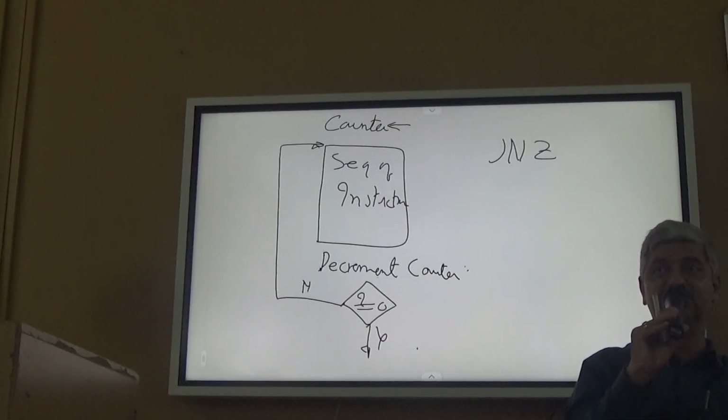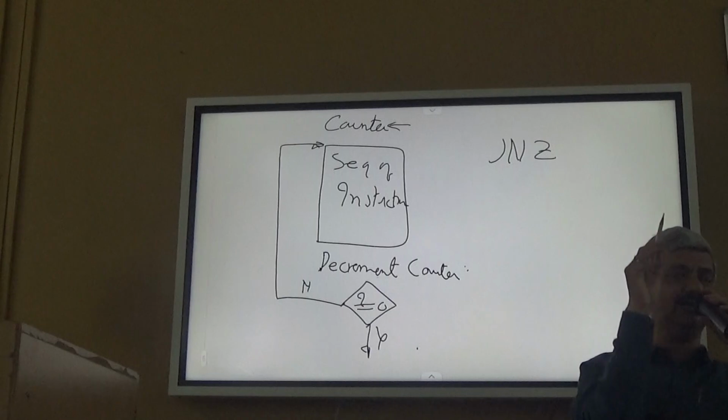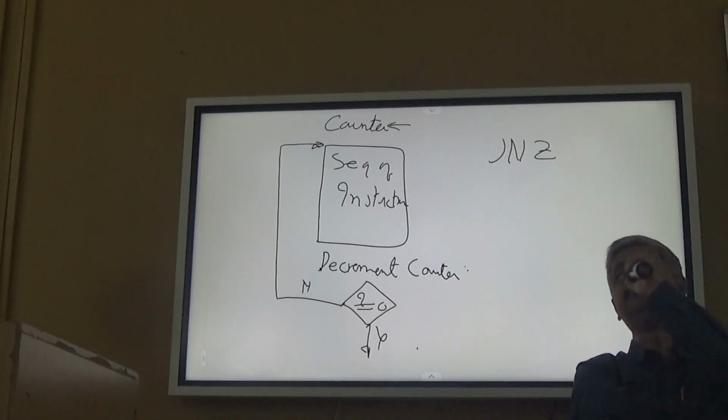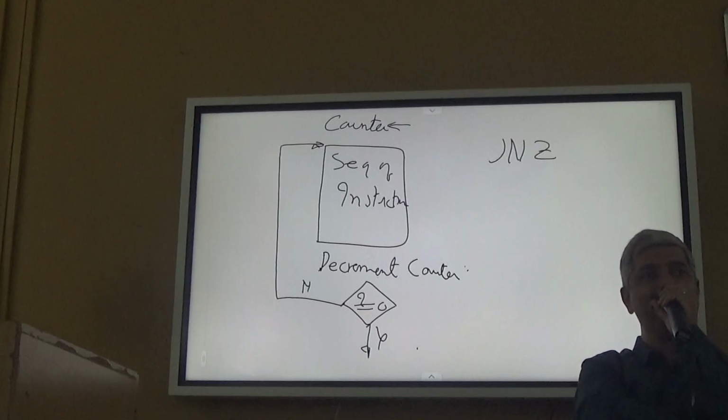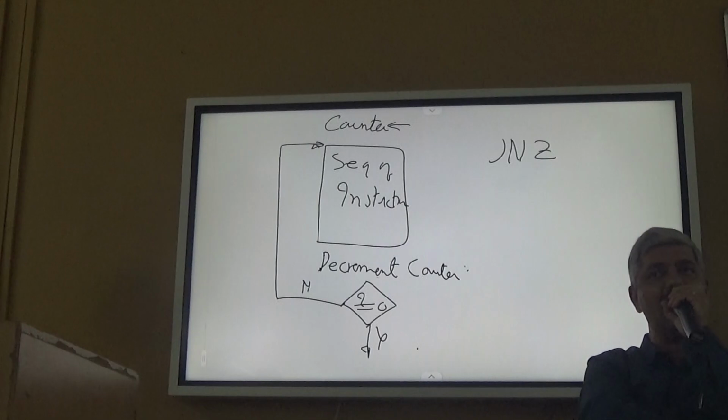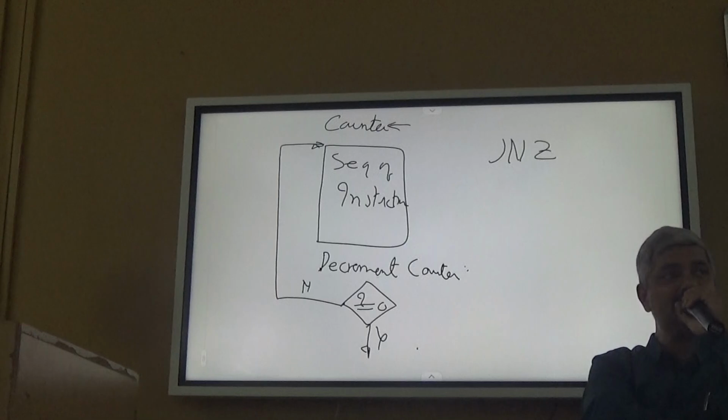Other flags we will discuss later. Zero and carry flags are affected after every arithmetic or logic instruction, and they provide the status of these two conditions when the last arithmetic or logic instruction was executed. Data transfer instructions do not affect flags.